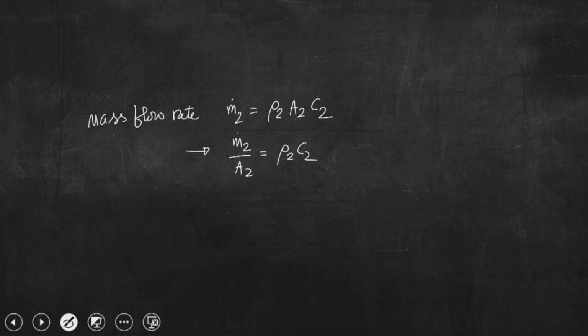Density will change with a drop in pressure, and that is modeled by the isentropic process equation. If we would like to maximize this quantity, we are in the process of maximizing it by having a suitable design of the nozzle. Essentially, it indicates that we need to increase the velocity of steam at the exit of the nozzle.